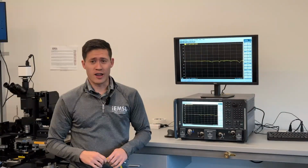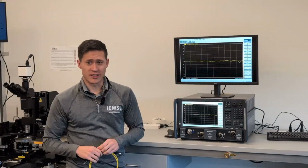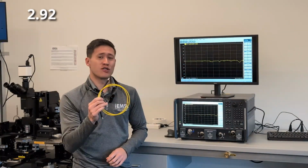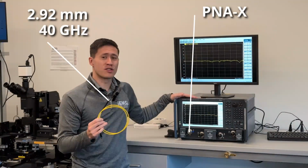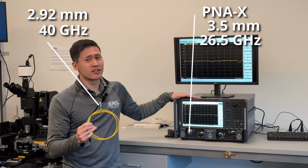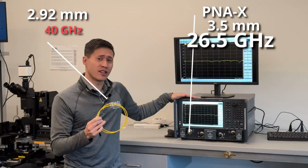This isn't just true for cables, but also for adapters and equipment. If I were to put this 2.92 millimeter cable, which goes up to 40 gigahertz, on the PNAX, which uses 3.5 millimeter, I'm still going to be limited to 26.5 gigahertz.